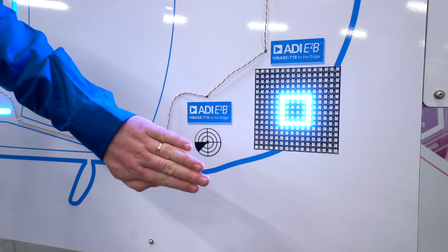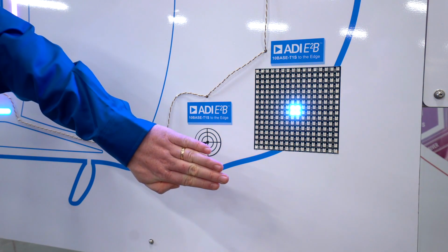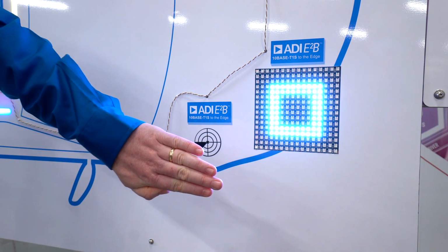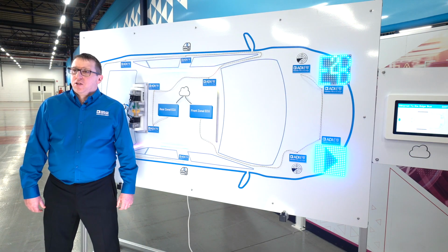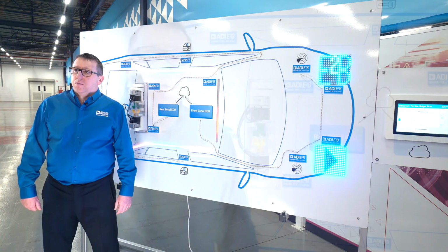As I approach one of the radar sensors with my hand, data is sent back to the zonal ECU, where the distance information is calculated, and the information is then sent back to the LED strip over the 10BASE-T1S network to reflect the distance. When no presence is detected, the LED matrix returns to a static pattern. This showcases a low latency control loop for headlight functionality with the software centralized back in the zonal ECU.